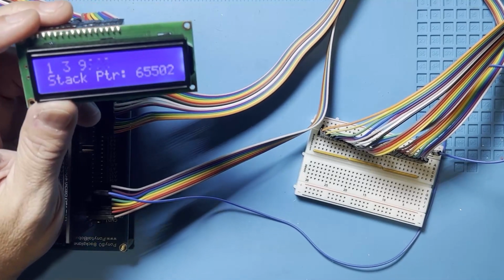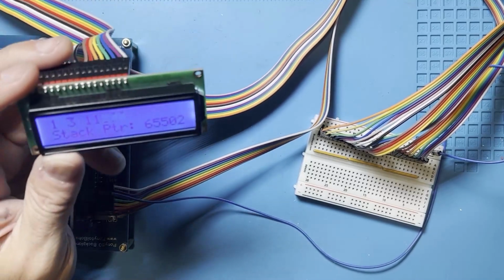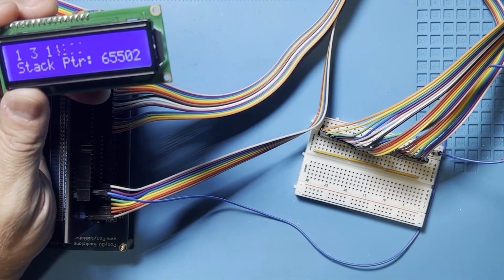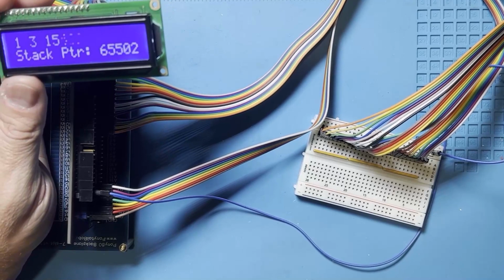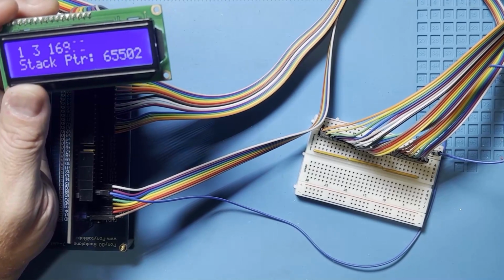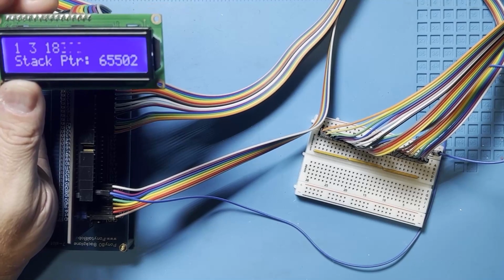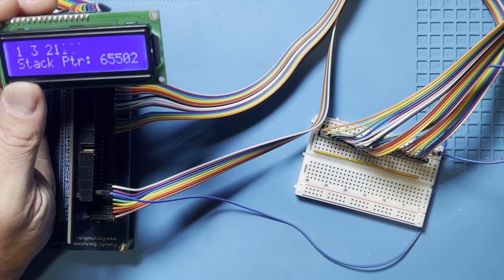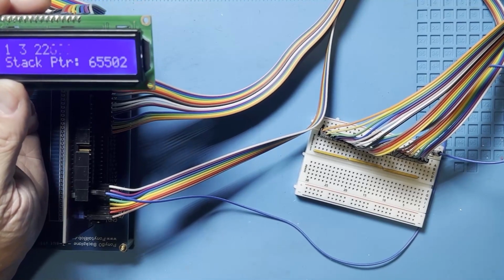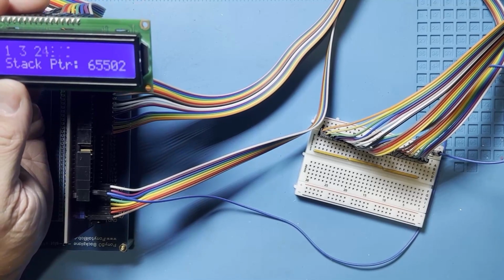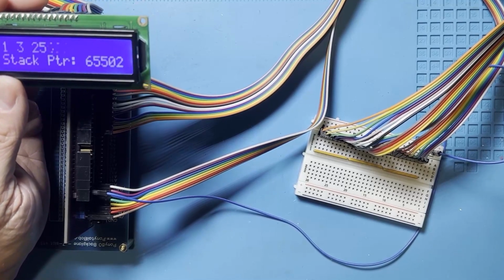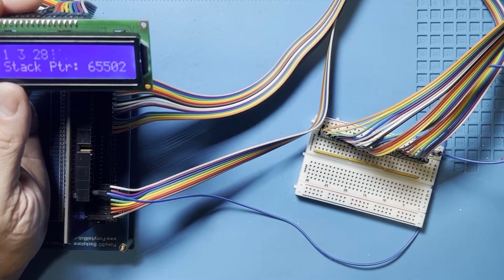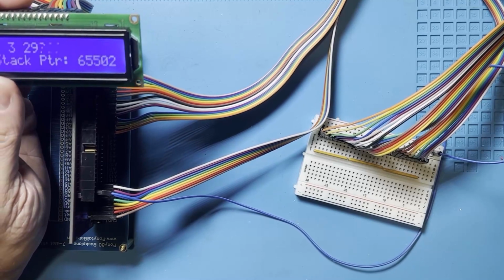Of course, I'll have some more hardware, because the next module we want to develop is the timer module, which will give us, I don't want to say a real-time clock, but it'll give us a consistent clock no matter what the oscillator speed is for the CPU module. So we could be running at 10 megahertz or at 1 megahertz, and this timer module will count consistently because it has its own oscillator. That's helpful because we can do delays and stuff like that. We can do some timing stuff.